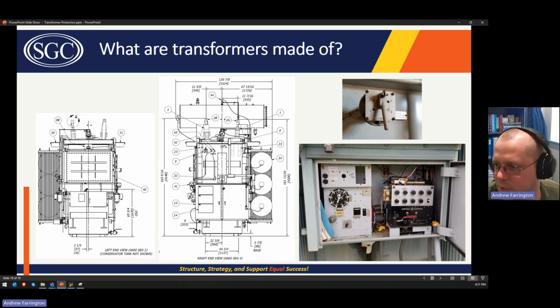Well, this one doesn't get pushed back. It stays right where it left. So this shows you the minimum tap and the maximum tap that the LTC has moved between since the last time it was reset. So this particular LTC looks like it operated between maybe 1 or 2 lower and about 5 raise, and neutral is within that area.